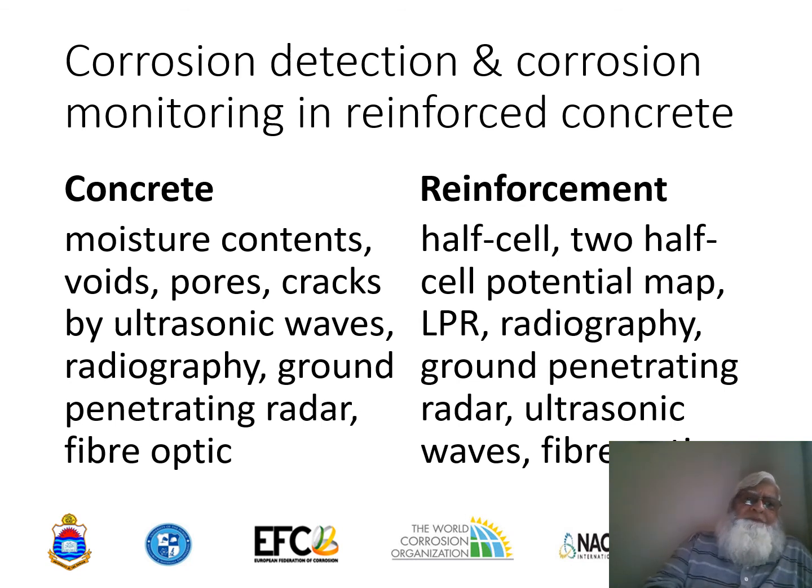And then the voids, pores and cracks are detected by techniques such as ultrasonic waves, radiography, ground penetrating radar, or fiber optics, which are used to monitor or detect if concrete damage is coming up, like the number of voids or pores having increased, or cracks having formed. These techniques are quite commonly used in the industry at present.